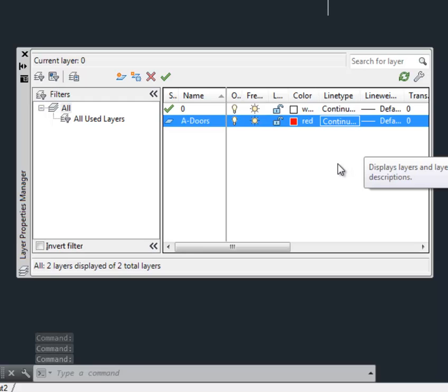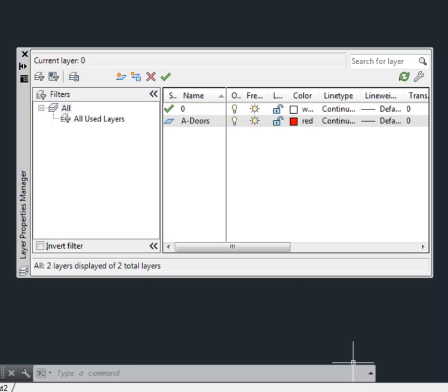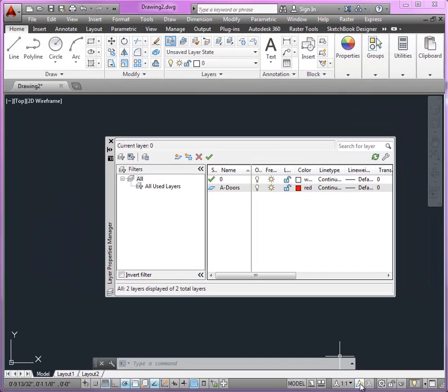So I'll go ahead and fill in these, and then we'll continue with the next part in the next video, part 2, design development. Once we've completed the layers here, before you start drawing, I want you to pay attention to your scale, your annotation scale. Before you start drawing, you're going to want to make sure that you set this and that you turn it on. I'll start with this point in the next video.